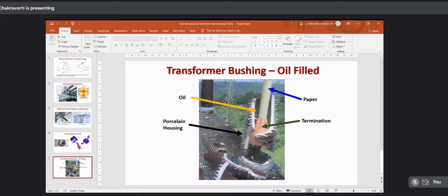So the point where this goes through the transformer tank is the most dangerous point for breakdown, because you have the high voltage conductor which may be at 400 kV, then you have the tank which is at zero. So you can see only this gap is withstanding that potential difference. So the design has to be very critical here. If you can see my mouse moving, that's exactly where it has failed.